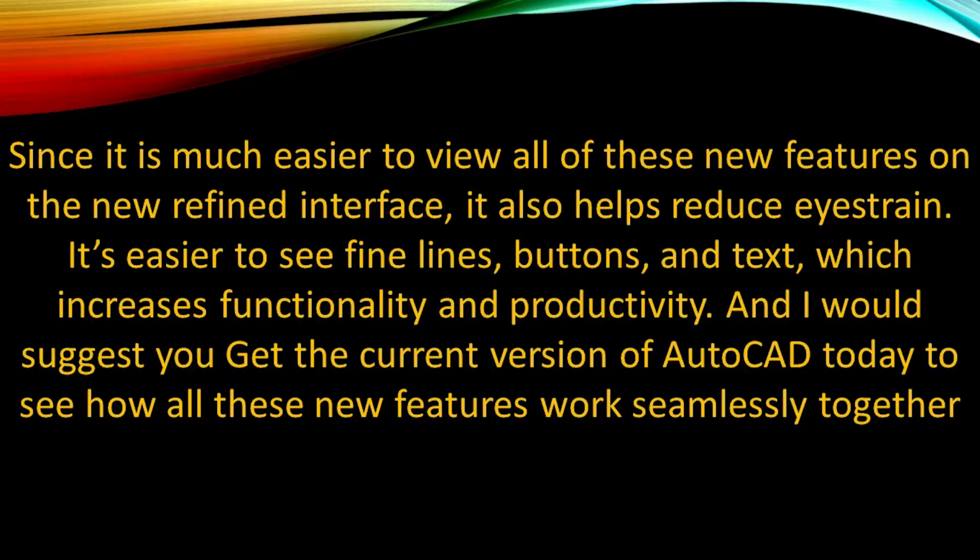It saves time. Instead of you looking for where the object is, you can just type them like TR for trim, O for offset, and so on and so forth. I'm going to show you all that on the screen so you can understand better what I'm displaying. Now, since it is much easier to view all of these new features on the new refined interface, it also helps reduce eye strain. It is easier to see the fine lines, buttons, and text, which increases functionality and productivity.